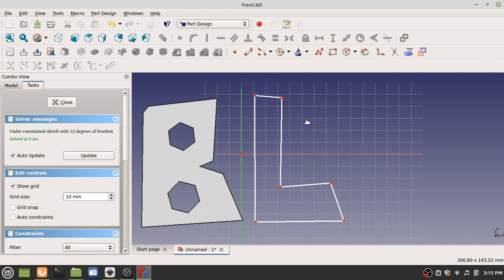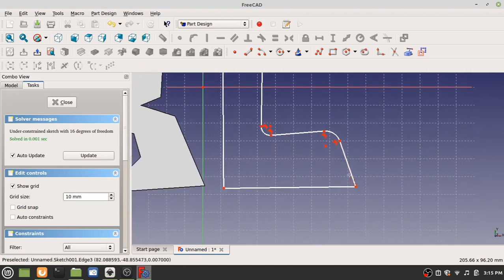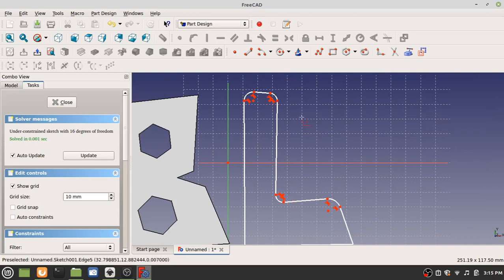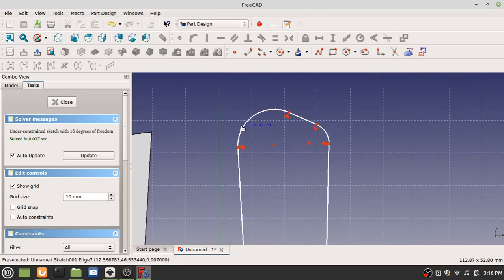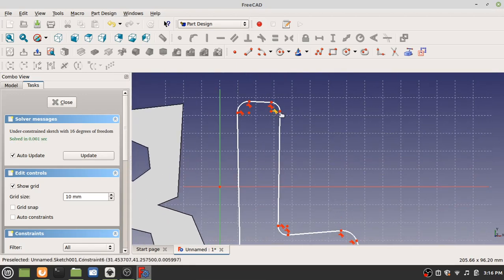I want to show you one additional technique. It's called the fillet. Yeah, fillet. Click it. It's next to the X. What that does is you can select 2 lines, and it kind of gets those 2 lines and curves it out. So if you want some lines to be curved like this, right click to move. You can just do that, and it kind of makes it round. Right click to deselect, and then you can manipulate by dragging the curved parts or the points to change the shape of everything.